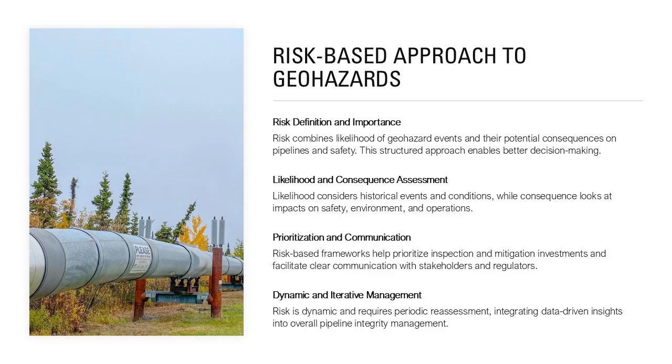Consequence assessment considers potential impacts on public safety, the environment, pipeline operations, and company reputation. High-consequence areas, such as densely populated regions or environmentally sensitive zones, warrant particular attention even if hazard likelihood is relatively low. Risk-based frameworks support transparent prioritization, enabling engineers and management to justify inspection, monitoring, or mitigation investments. They also facilitate communication with regulators and stakeholders by clearly explaining why certain locations are addressed before others. Importantly, risk is dynamic and must be periodically reassessed as conditions change or new information becomes available.